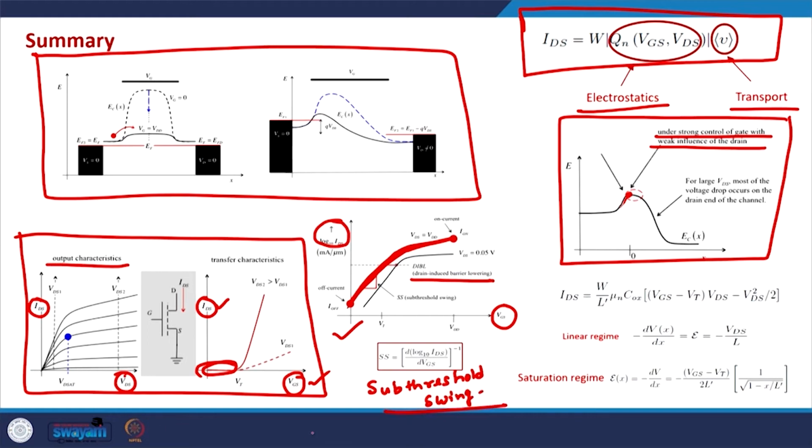The sub-threshold swing is defined as the amount of gate voltage that is required to change the drain current by a factor of 10 below the threshold voltage.